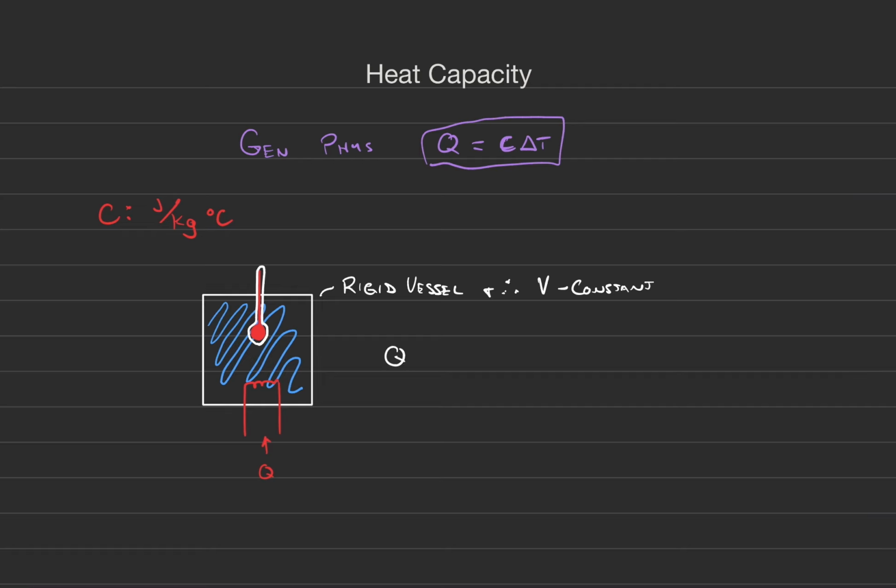So we end up with that equation above, but we're going to actually use its differential form. And we're going to use its differential form because, unlike in general physics, the heat capacities aren't always constant with respect to temperature. We'll assume that they are in many cases, or at least an average heat capacity will be used.